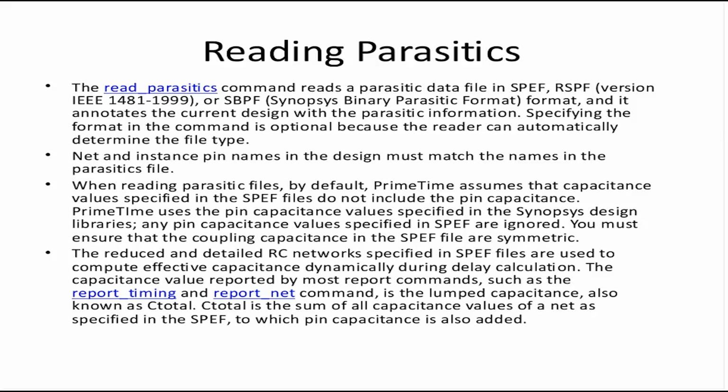When reading the parasitic file, by default PT assumes that the capacitance inside SPEF does not include the pin capacitance. The pin capacitance value always comes from the standard cell attribute. Again, delay has two parts: cell delay and net delay. A cell has delay represented in a lookup table, but it also has capacitance on the node.